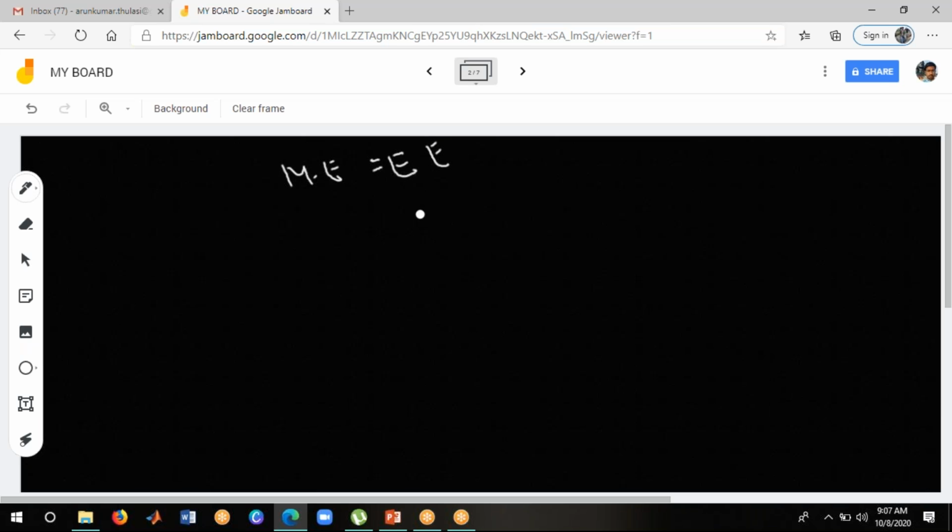This is called the energy balance equation at equilibrium condition. It means that there are no losses. So now we are going to find the armature torque. I can represent torque as TA, the armature torque, into omega equals the electrical energy available on the armature, which is given by back EMF into armature current. So this is the energy balance equation at equilibrium condition.